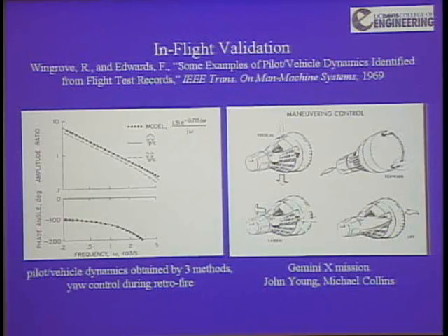Here is some work. This is a space ed, so I better bring in a spacecraft. This is a paper written by two former colleagues of mine back at NASA, the late Rod Wingrove and Fred Edwards, called Some Examples of Pilot Vehicle Dynamics Identified from Flight Tests, published in the IEEE Transactions on Man-Machine Systems. This is John Young and Michael Collins in Gemini 10, and they were controlling the yaw motion of Gemini 10 in retrofire. Rod and Fred measured the pilot vehicle dynamics again. What do you see? Minus 20 dB per decade, high frequency phase roll off due to time delays.